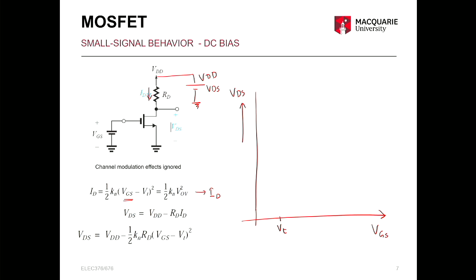So in this equation, this term is equal to 0, or looking at the circuit, ID is equal to 0. So there is 0 volt dropped across RD, which means all of VDD is available at the output. That happens until the voltage VT is reached.